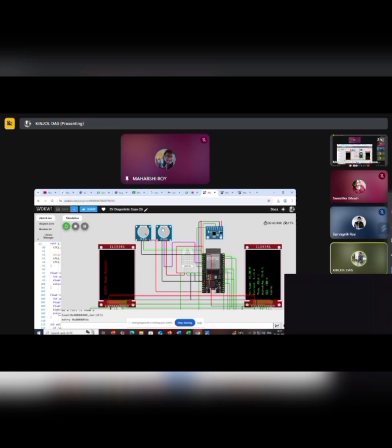Whenever the battery usage is high, the current usage is also high. So we simulate this current usage by changing this potentiometer. Like you can see, here the current increases to 19.4 amps. Here the high battery usage alert will pop up, like here, high battery usage. So this will create a notification to the driver. At that time, we can change our speed and maintain our battery life for longer. So this is our program, and now I'm going to describe the flow chart.